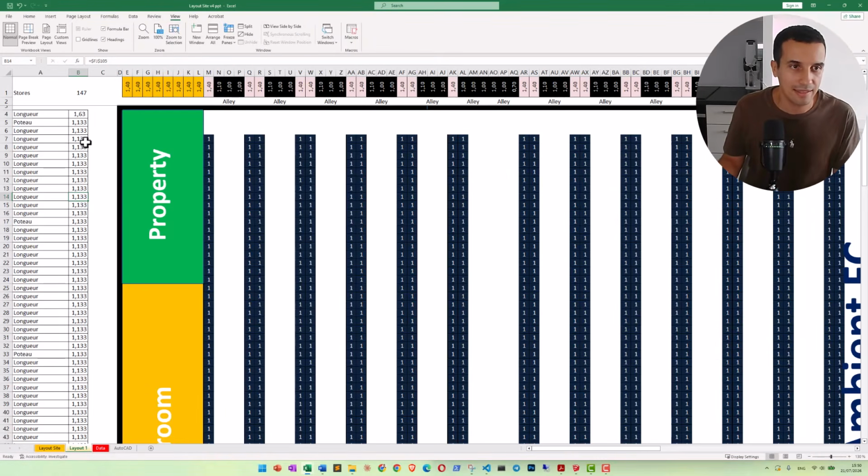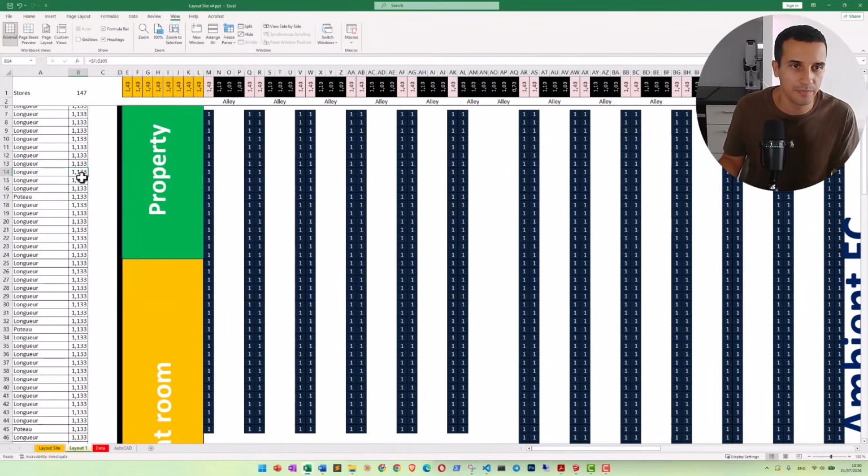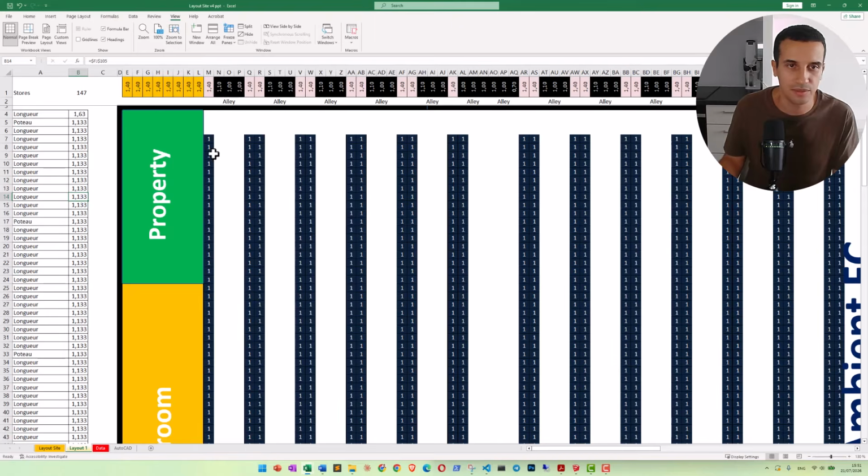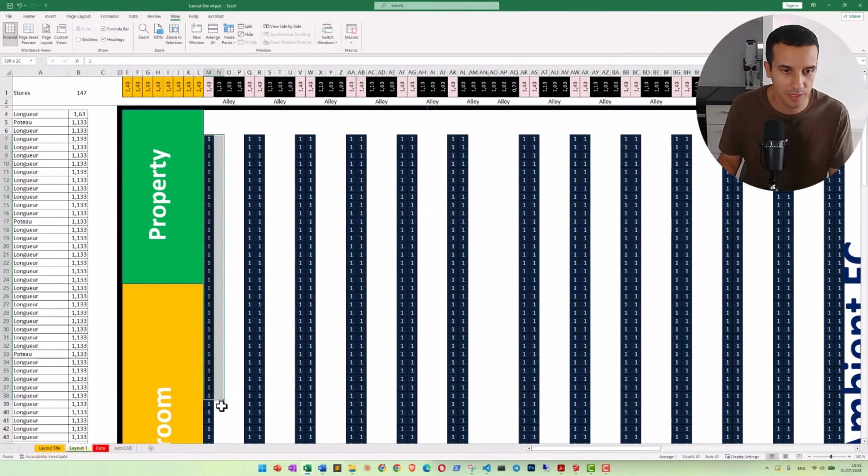So let's look in more detail at the different changes that I made. So here it was 1, now it's 113. Here, I have adapted the width because now I am putting racks, right? So this is a complete row of racks. These are 2 rows that are stuck. And here, this is the space between both. Normally, the space between both should be 3 meters. This is what I did here, but what you can see is 3.1.